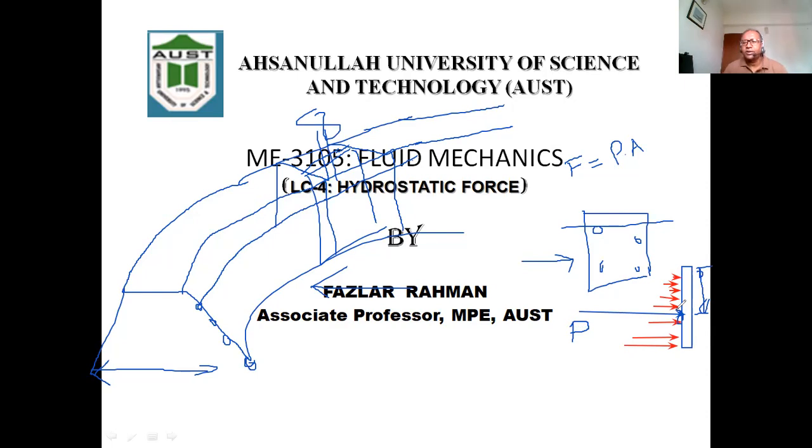then you can design the gate properly, because you have to make sure what the thickness of this plate will be, what type of material you use, and other things on both sides. Also you have to make the support strong enough that it will carry the load, because the pressure force ultimately works right over here in the plate, right?